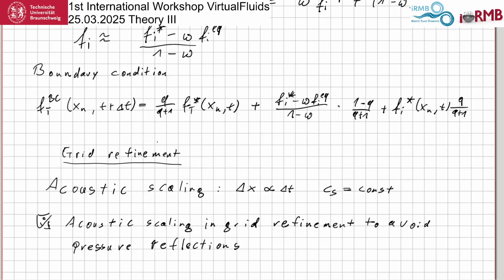So for people coming from the Navier-Stokes world, this means something else, because you may not even consider it necessary that you refine the time step together with the grid spacing, because in many codes, like in CFD software, usually you have a global time step that does not care about the grid spacing. In the Lattice-Boltzmann method, you usually have nested grids. Yeah, so they are all Cartesian grids, and when you refine the grid, you also refine the time step.